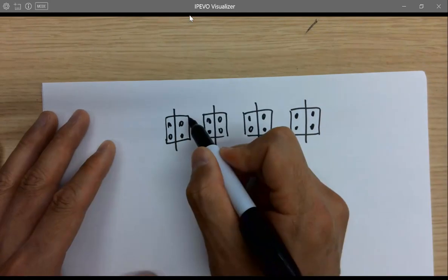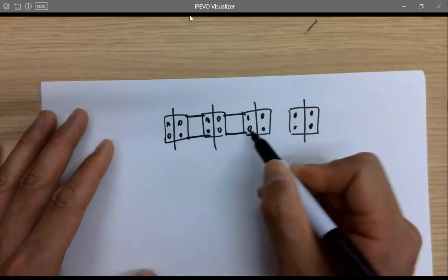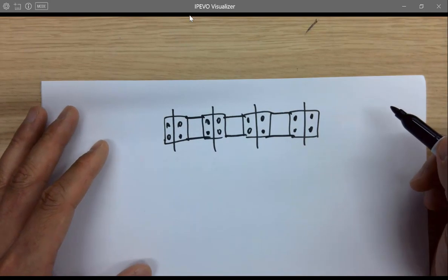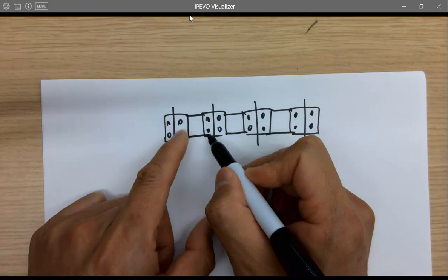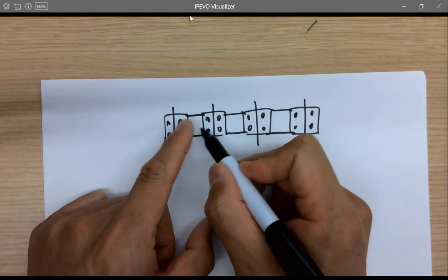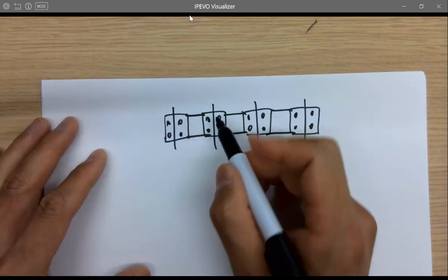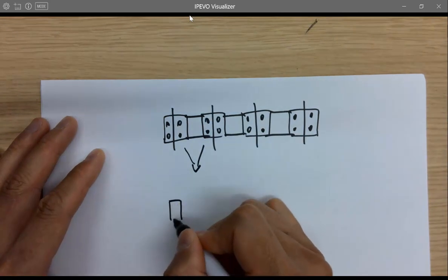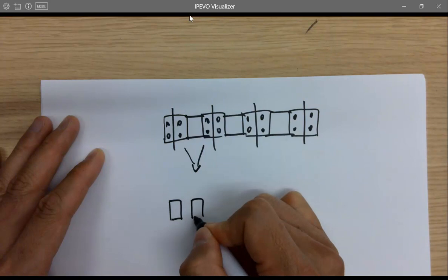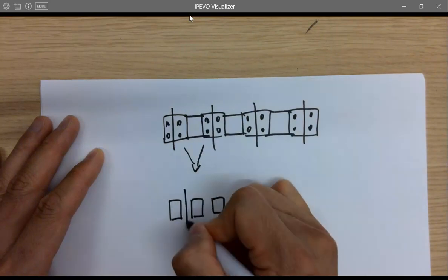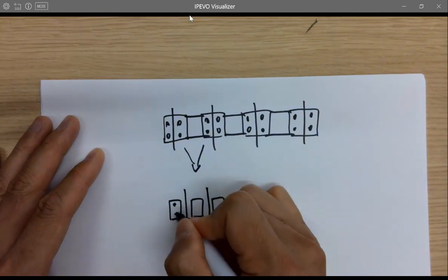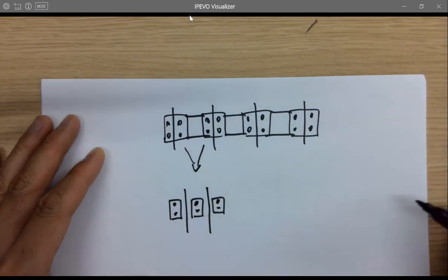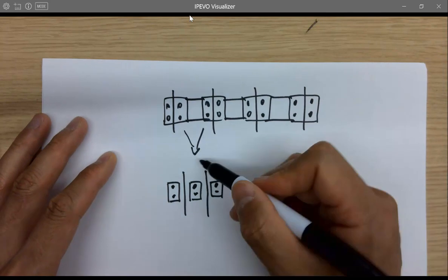You can draw the green diffusion, connect them together, and find out you get two diffusions. They are basically doing nothing. It's just redundant, so you can merge them into one, right? So eventually it becomes this. So two becomes one.